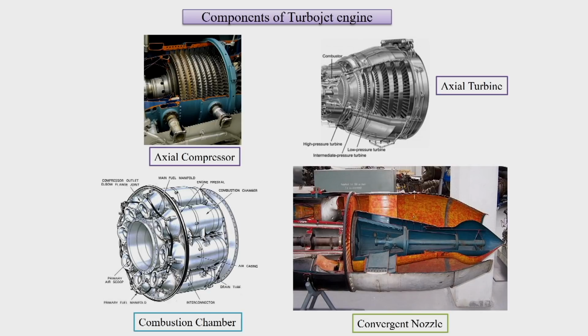So as we see, here we have the nozzle. The nozzle is an additional entity. It is only for propulsion, but one thing especially written over here is a convergent nozzle. Nozzles can be of different types, and those types depend upon the exit condition which we are going to create. The convergent nozzle has a limitation: at the entry we have a very low velocity subsonic flow, but it has very high pressure and high temperature.